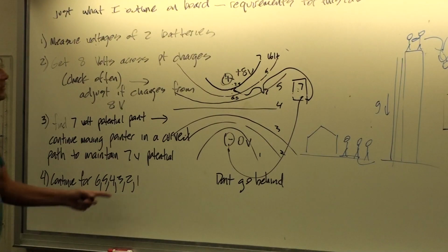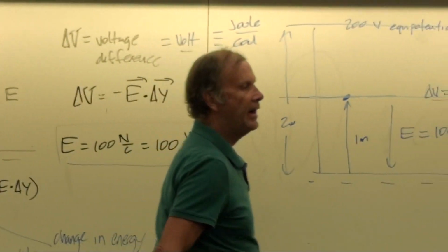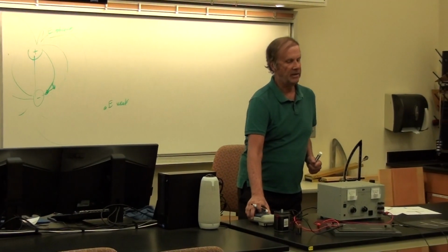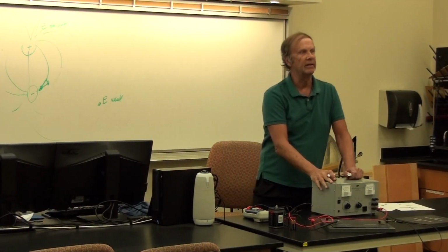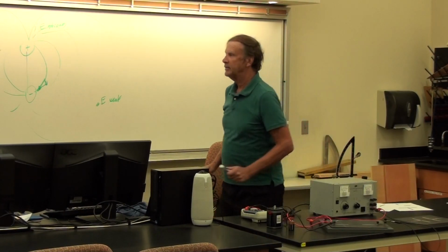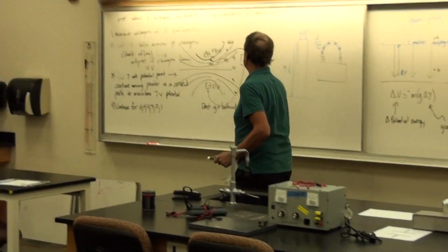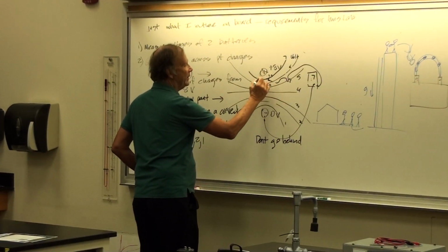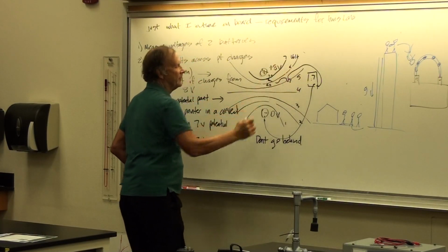Okay, and so now you've got your voltage field. This is a scalar field. It doesn't matter which way I orient the meter, it's still going to be that number of volts. Now, the gradient of a scalar field can be a vector field. And so that's where we get the electric field. And so you can imagine this to kind of be like lines under topography now. Okay, so this might be your low point here. And so then if you go up this way, it's kind of like climbing a mountain. But if you go this way, your slope isn't as steep.